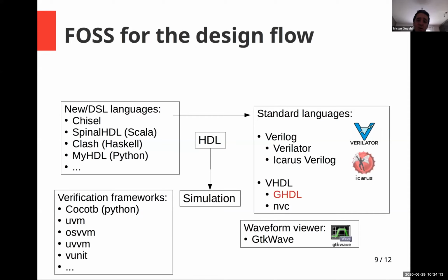For Verilog, you have Verilator, which is a very high speed tool that translates your Verilog or SystemVerilog input into a set of C++ files that are then compiled and executed.